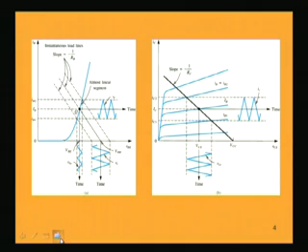So, now again if we look into the AC and DC components and the overall instantaneous currents and voltages, then we see in these plots, when only DC conditions prevail, suppose we are not giving the signal as such till now, only the biasing voltages are there, then due to the DC biasing the input circuit is forward biased and the output circuit is reverse biased.